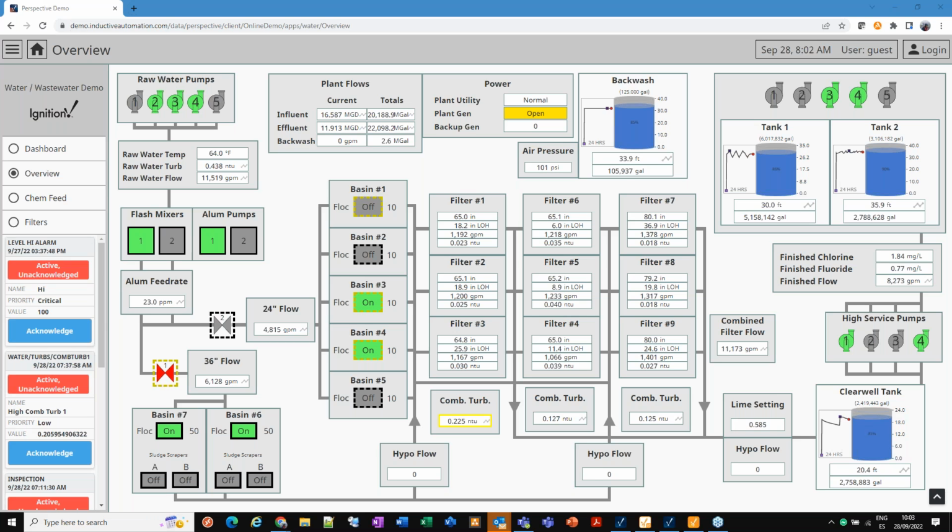And then it depends on the device itself as a source. Some devices have a bit of buffering. Not all, and that depends on the manufacturer, but most of them have some buffering. So if there's a network breakdown or breakage, it buffers and will send later. So Ignition will get the data with its own timestamp and refill the missing gaps. I don't know if that answers this question.